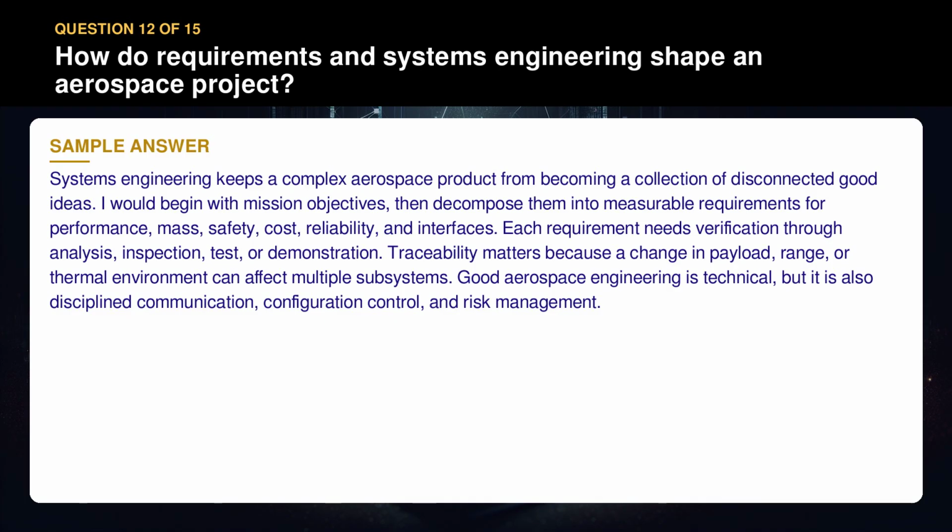Systems engineering keeps a complex aerospace product from becoming a collection of disconnected good ideas. I would begin with mission objectives, then decompose them into measurable requirements for performance, mass, safety, cost, reliability, and interfaces. Each requirement needs verification through analysis, inspection, test, or demonstration. Traceability matters because a change in payload, range, or thermal environment can affect multiple subsystems.